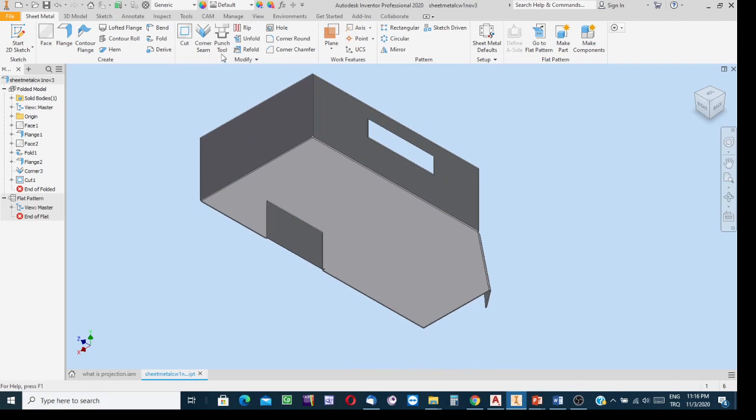Okay, now how about punching? Well, make a demo to explain the function of this one. It is a drawing process, deep drawing. While you're holding the sheet metal, then you're applying a force, deformation force, and since you are using a special ram in special shape and size, then the created feature, which is going to be a combined feature, going to be say special emboss. Okay, just plastically deforming the sheet metal. Okay, the technology we say deep drawing, we can create embosses.